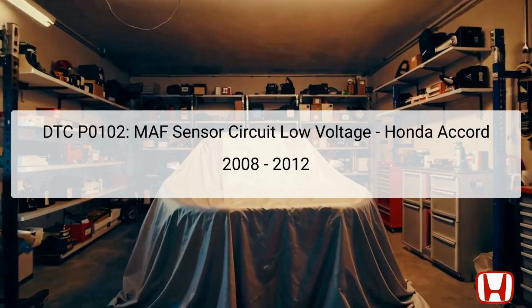The Honda Accord models from 2008 to 2012 may encounter diagnostic trouble code DTC P0102, indicating a low voltage condition within the mass airflow MAF sensor circuit. The MAF sensor is a critical component that measures the amount of air entering the engine. Its precise measurement helps optimize the air-fuel mixture for efficient combustion and engine performance.